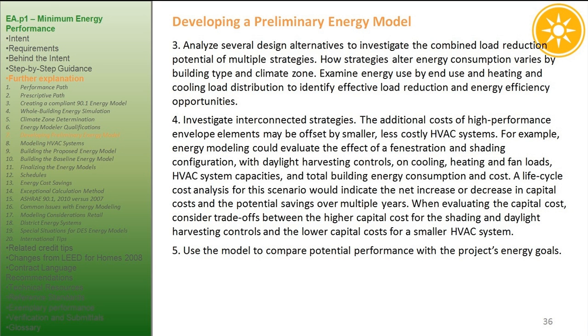For example, energy modeling could evaluate the effect of a fenestration and shading configuration, with daylight harvesting controls, on cooling, heating and fan loads, HVAC system capacities, and total building energy consumption and cost. A lifecycle cost analysis for this scenario would indicate the net increase or decrease in capital costs and the potential savings over multiple years. When evaluating the capital cost, consider trade-offs between the higher capital cost for the shading and daylight harvesting controls and the lower capital costs for a smaller HVAC system.